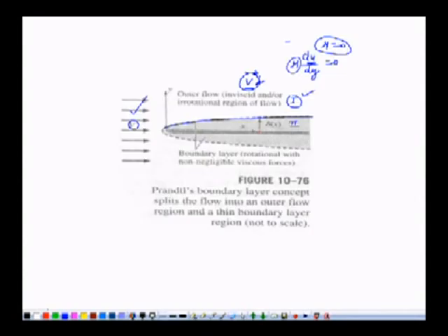It must be 0, and as we move upward in transverse direction, then somewhere the velocity becomes 99% of free stream velocity v. So here if velocity becomes 99% of free stream velocity, then this distance travelled in transverse direction, this is delta x because it is a function of x. So at different values of x we have different values of thickness. This is defined as a boundary layer thickness, this delta is defined as a boundary layer thickness, and this is a function of x, because at x equal to 0 its value is almost 0, and as x goes up its value also goes up.